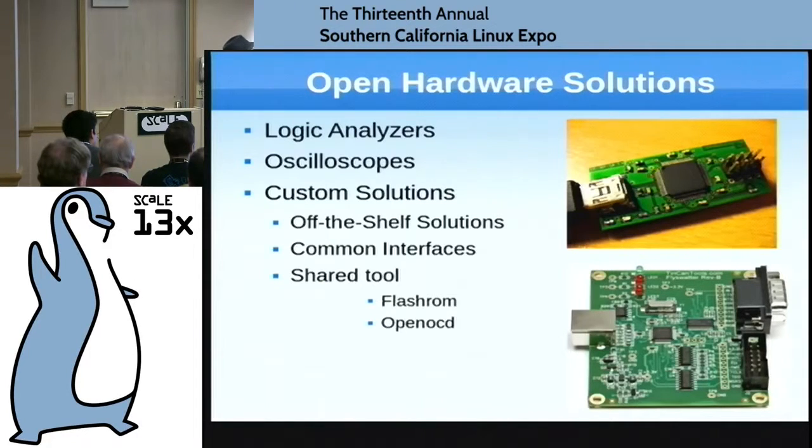Now, FlashROM supports a USB protocol that allows you to build your own board to program the SPI flash. There are several different shared files that you can go out there and get custom schematics and create these to work specifically with a software package. Another example of this shared aspect is, for instance, the FlySwatter JTAG board. This was built around specifically working with the OpenOCD application to do JTAG debugging and flashing.